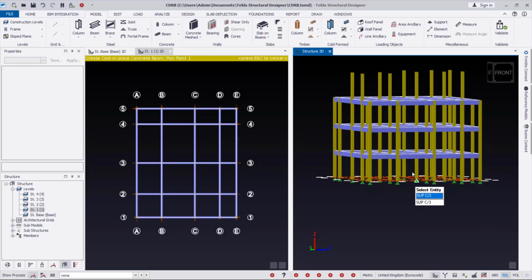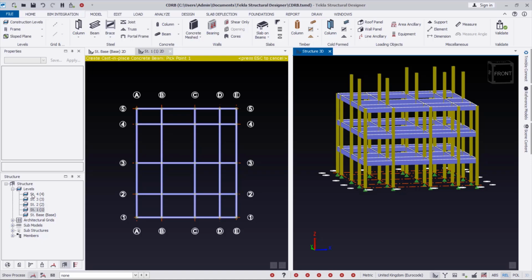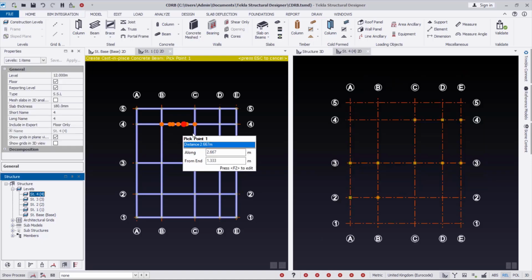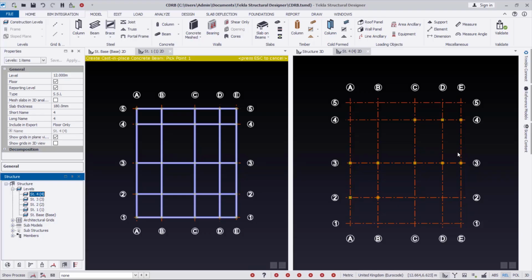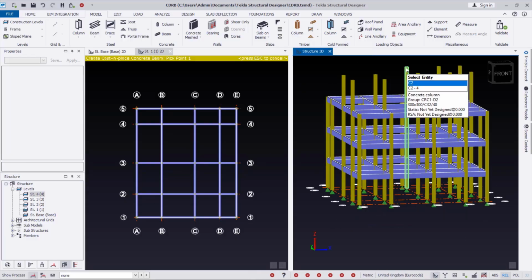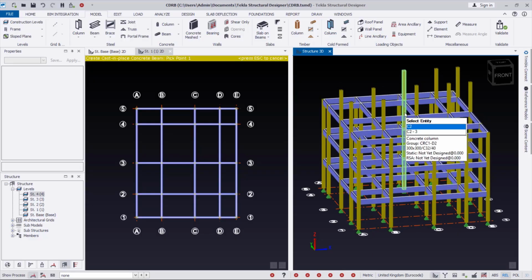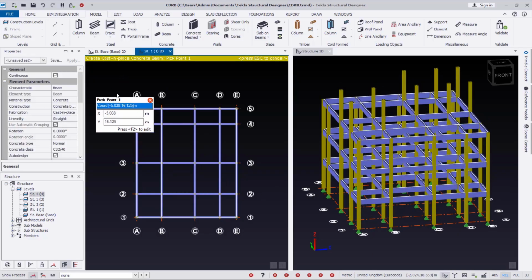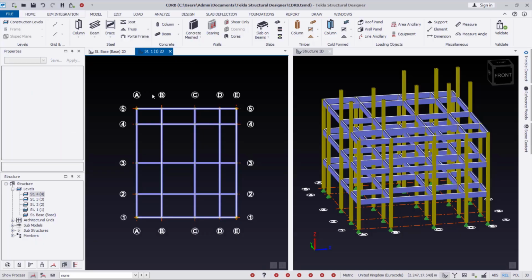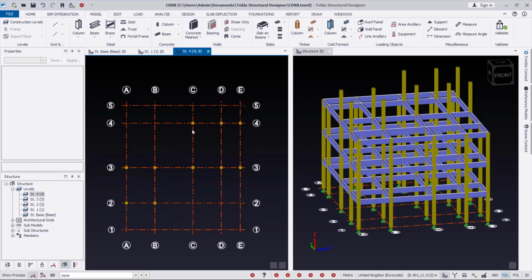Now we want to place the beam at the topmost story here. You need to navigate through these provisions, double click here to get to the top story. You see this has changed here because we have already activated this provision before we actually double clicked on the ST4. So we can close this from here to get back to 3D, because we are going to review from here the 3D. So I click here to activate this, escape to get rid of the previous command, and then I double click here. This will take me to story 4, which is the last floor.